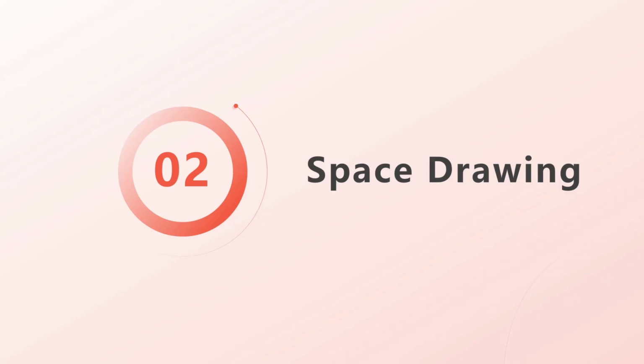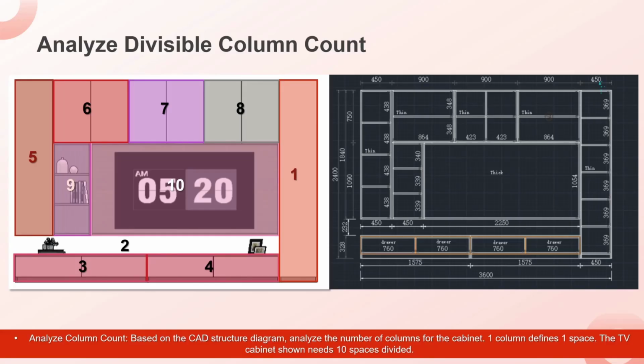Now let's going to talk about the space drawing. For the space drawing, it's generally suitable for some kinds of cabinet like this. You can see from a single view, see all of the fronts of all of the cabinets. Then you can use space drawing to create this cabinet. To drawing this cabinet, you need to divide it into the different area first. Like the right side is one of the space, and here the second one for this drawer, the 3 and 4 space, and the others.